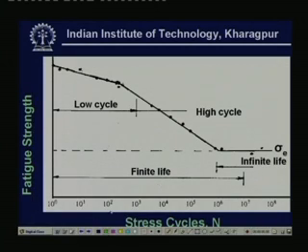So, in this case, if you lower down the fatigue stress up to a point somewhere here, then within this zone, even if you are giving a varying load like that and the stress generated onto the machine member is within this zone, then the material can withstand an infinite life.